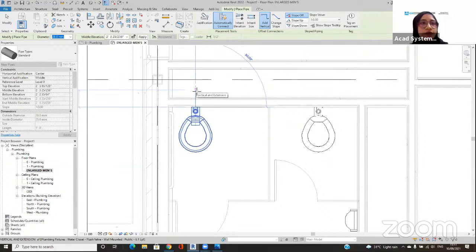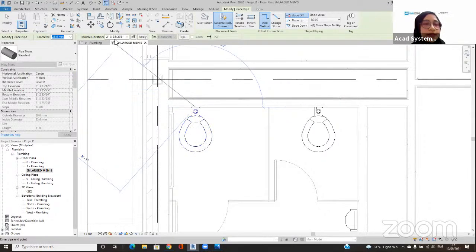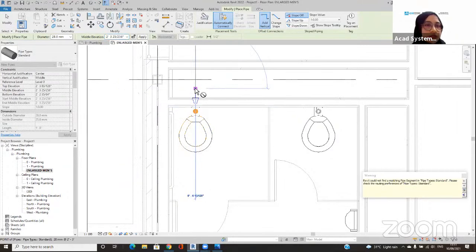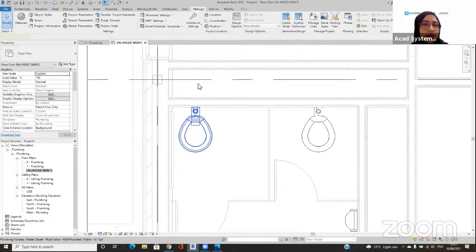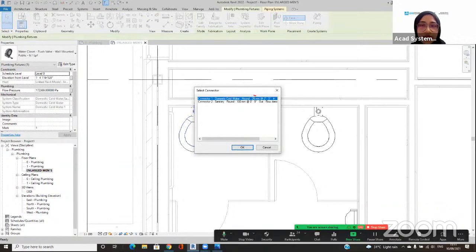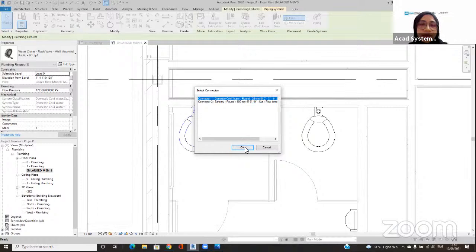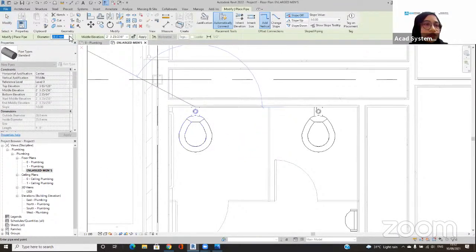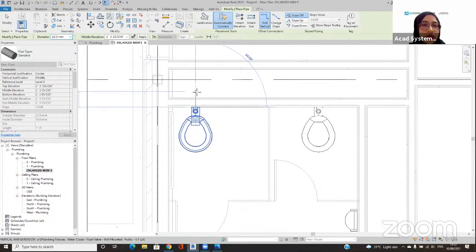Okay, I'm going to continue here. Draw the middle elevation, that's fine for me. So I'm just going to draw from here. Oh, just now I forgot to change the diameter again. Let me start again from here. Because if you see, it only allows up until, because we specified it to be the minimum 25 mm diameter, so I have to change it here to slightly more. I hope this will work.